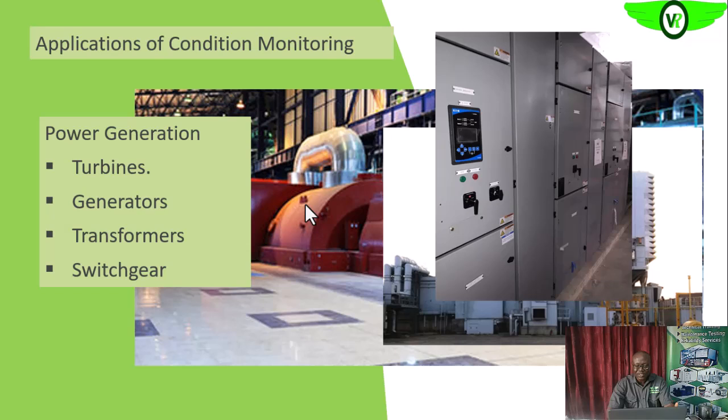Within the switchgears we have conductors, breakers, and current carrying components. As we'll see later, we'll go into infrared thermography. A condition monitoring technology like infrared thermography will help us see the condition of the components of the switchgear.